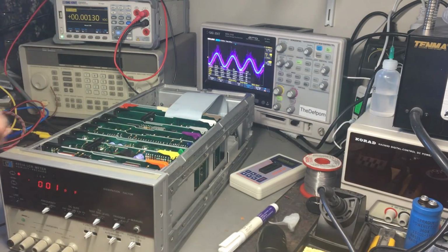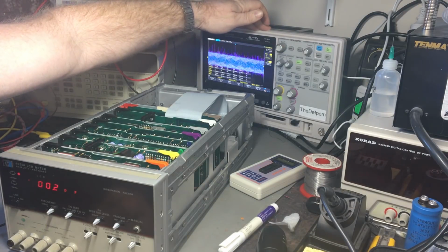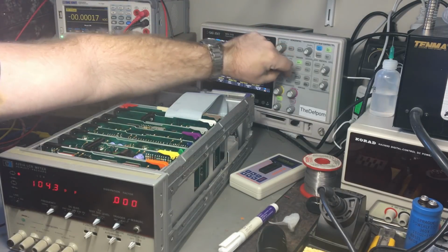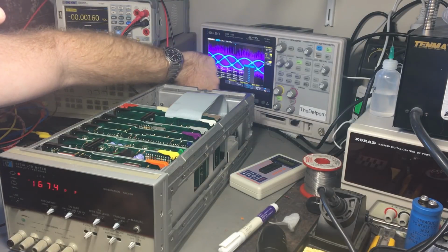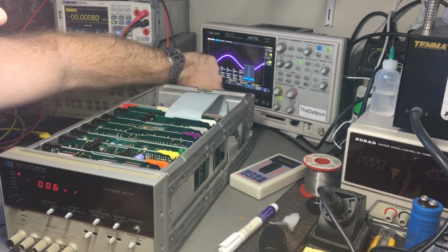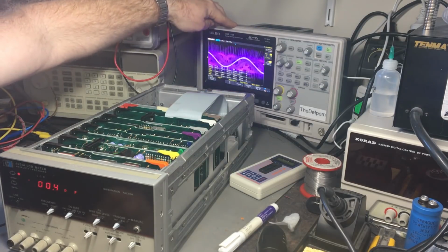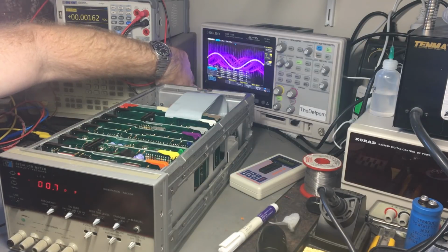Anyway, it's measuring a frequency. If I change this to 1 kilohertz, the frequency changes too. And the scope is having trouble reading it because there's so much noise. Let's increase the memory depth. Anyway, it drops down like that. Oh, gone too far. There you go. That may help. Peak detect, no, I don't want that.